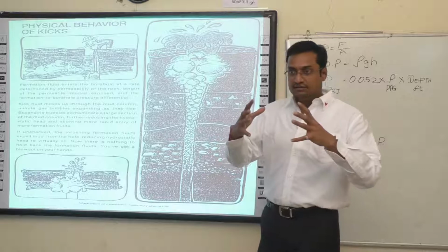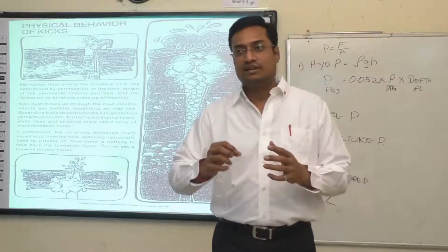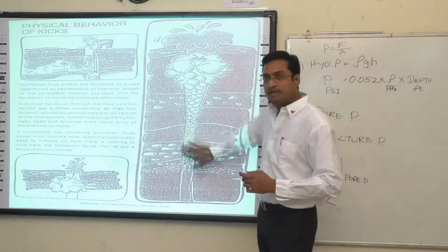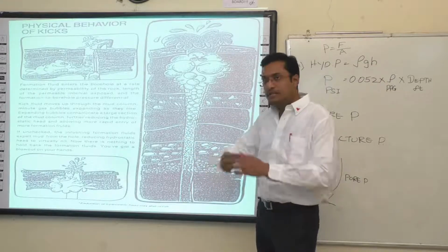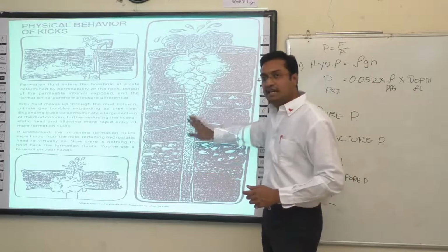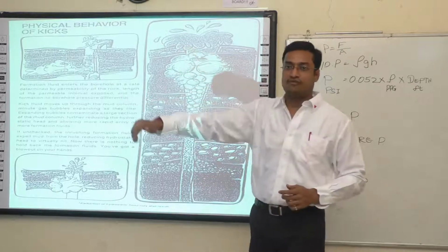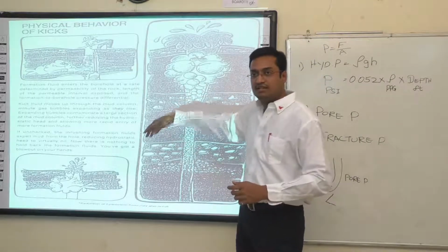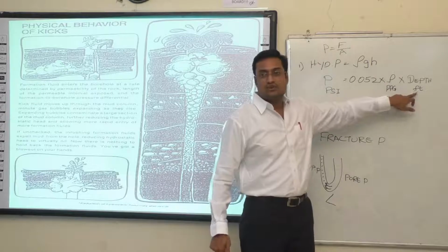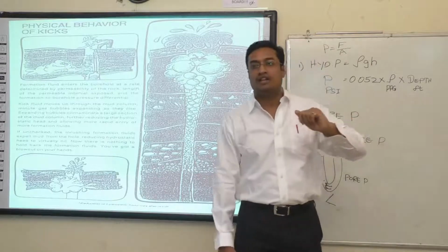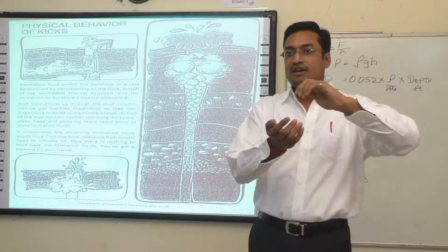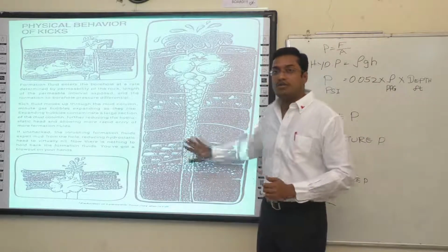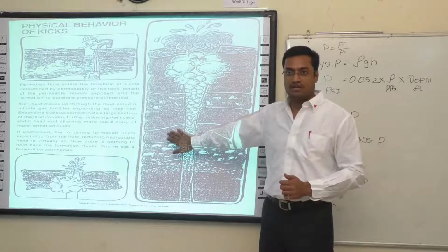When it is expanding, the pressure has to reduce. So the high pressure, when it comes inside the wellbore, reduces, but the volume increases. When the volume increases, it displaces more drilling fluid. So the total height of the drilling fluid starts reducing, and the underbalance condition becomes bigger, and you get a continuous flow of formation fluid into the wellbore.